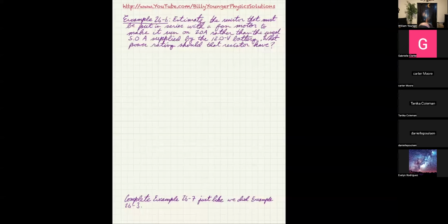All right. So what we're going to do first is try to see exactly what kind of resistance the motor has, specifically by realizing that probably the only thing in series with the 12-volt battery and the motor is basically the wire and the motor itself. So what we're going to get is resistance that accounts for the resistance of the wire plus the resistance of the motor. Probably most of that would just be the resistance of the motor, but we'll see. So, solution.